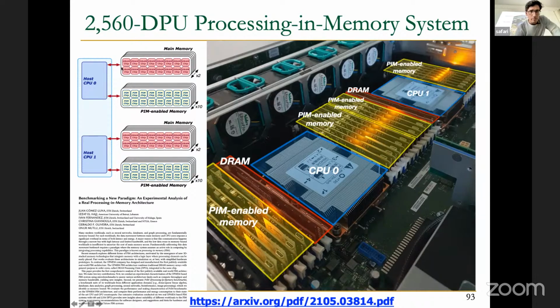So there is still main memory, but we also have the PIM-enabled memory that now behaves as an accelerator that has very large compute capability because there are many, many cores, 2,560 DPUs, or 2,560 PIM cores, or small processors near the memory arrays, and also large memory capacity, around 160 gigabytes of PIM-enabled memory that has this AppMem system.